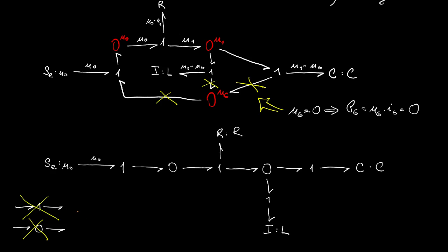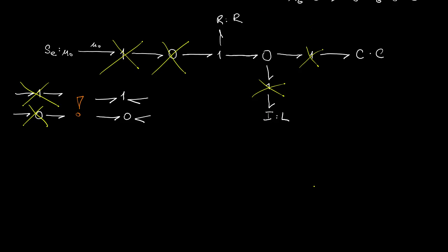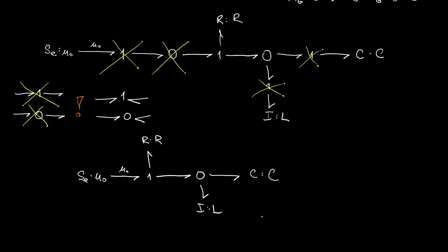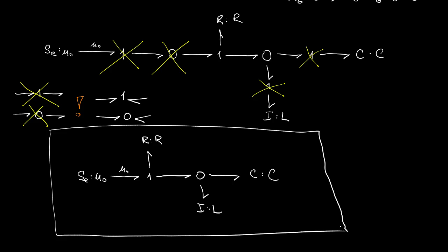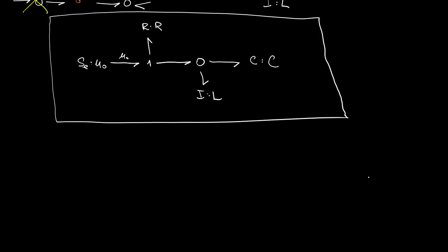Obviously, we can make one more simplification here. Whenever we have type 1 or type 0 junctions with just 2 bonds, we can eliminate them, provided the directions of half arrows is identical, which gives us the following resulting final bond graph. Voila, this is our first fair bond graph that we succeeded in constructing.